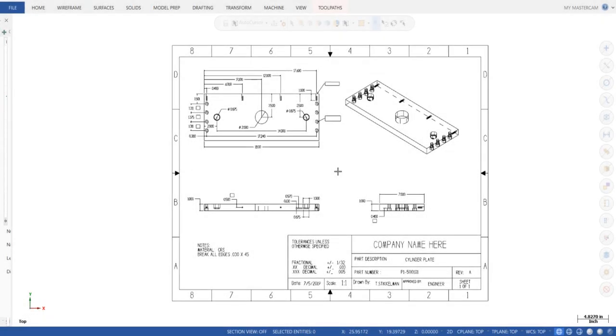Alright, in this session I'm going to talk about blueprint reading, and most likely the majority of you read blueprints every day. What I mainly want to talk about is looking at blueprints from a CNC programmer standpoint. When a blueprint is handed to you, what information do you start looking for as a programmer? The first thing I would look at obviously is the part shape and determine whether it's a mill or a lathe job.